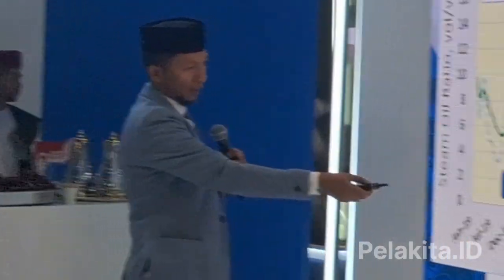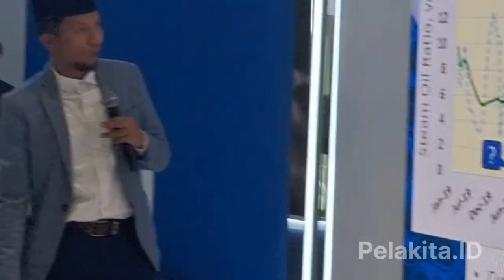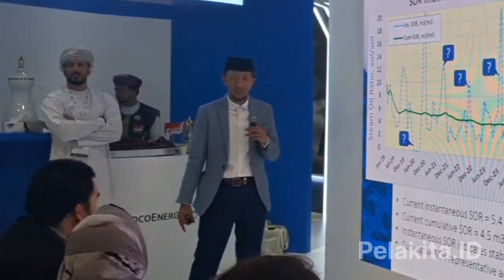So what happens during this hunting, the lows and downs of the steam oil ratio, like this one in June 2020? We have a low, even 0, instantaneous steam oil ratio, because at that time we stopped the steam injection for economic reasons. At that time the oil price was less than $25 per barrel. So that's why it's not economic to run this project. So we stopped the steam injection.